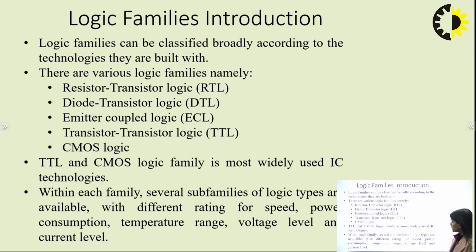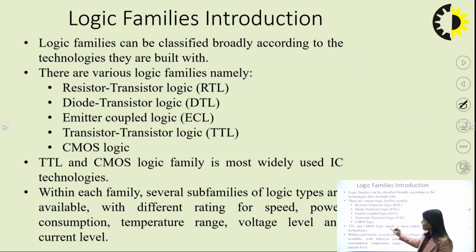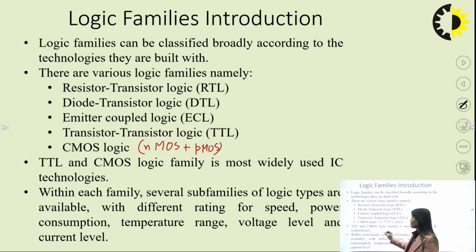So combining these, we can make the digital circuit, that is, NMOS plus PMOS. Whatever circuit I make for the NMOS, I can reverse the circuit for the PMOS. So if NMOS transistors are connected in series, then PMOS transistors will be connected in parallel.